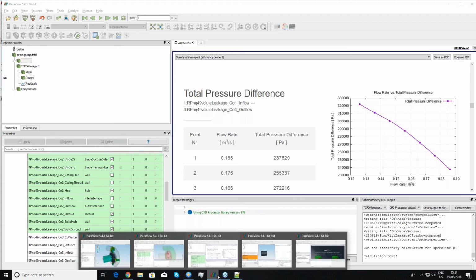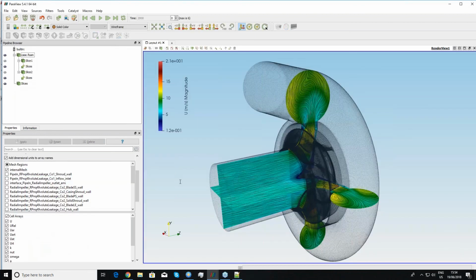He is asking whether one can give in CFturbo balancing holes during the design of the impeller. Very often they are introduced into the hub. Right now we cannot do that in CFturbo, but because everything what we do in the meridional contour is done under the precondition of axisymmetry, and this whole feature would not fit into that concept.